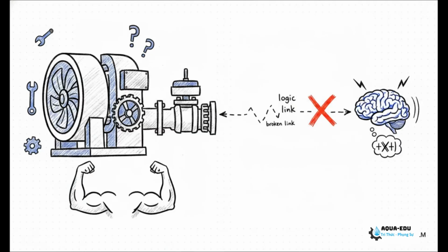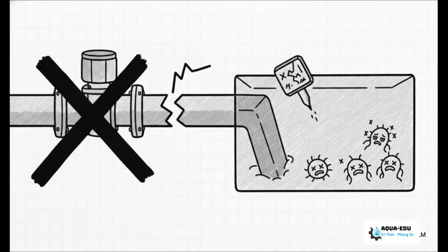When we're looking at this heavy mechanical equipment, your blowers and your motorized valves, these guys are the muscles of the plant. If your motorized control valves on this equipment simply do not respond physically when you send an open or close command from the SCADA room, that logic link is officially broken. The brain is no longer talking to the muscle. Let me just reiterate that. If valves fail to respond to commands out in the field or from SCADA, you need to take immediate action.